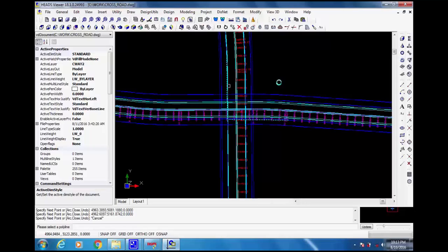As both the intersecting main roads are having service roads on either side, the polyline for the loop road is started and finished on the inside edges of the service roads, drawn in the direction of traffic movement. Here the UK system of traffic is considered. Essential lengths for deceleration and acceleration lanes are to be maintained in drawing the polyline at the start and end of each loop road.